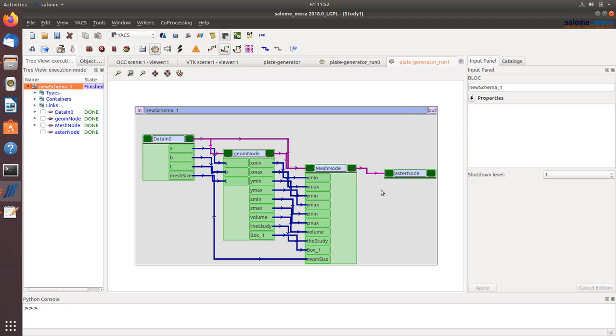And now maybe we can have a quick discussion about how you would make that parametric, because you see I showed you some way to insert some parameters here and to change in function of those parameters. What if I want to put some parameters for the simulation as well? Well, that would be a bit more complex, but it's doable as well. The only thing you need to know is that to modify the simulation, you need basically to rewrite the COM file. So you could think about adding a node, like another Python script node,